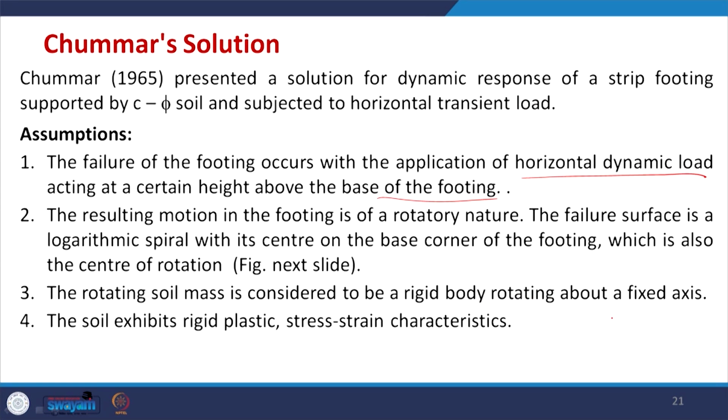Now, this was the second assumption: the failure surface is a logarithmic spiral with the center on the base corner of the footing, which is also the center of rotation. Third assumption: the rotating soil mass is considered to be a rigid body rotating about a fixed axis.